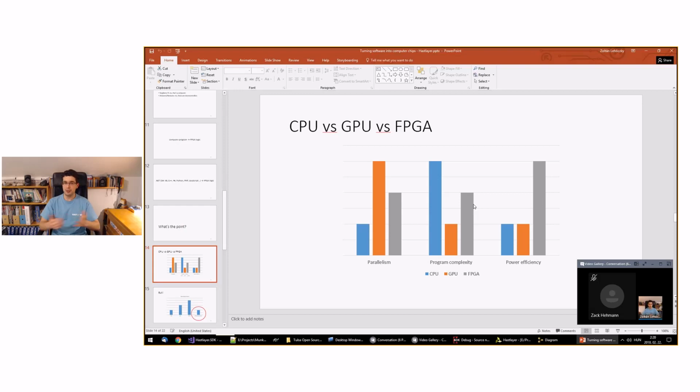As for FPGAs, you can hash out something fairly quickly, although FPGA development itself is 1 or 2 orders of magnitude slower and more expensive than programming. But with FPGAs, you can still roll out something fairly quickly. You can buy an FPGA for maybe a couple thousand dollars, but that's it. With ASICs, the development is much slower and much more expensive. You have to be very careful because you can't change an ASIC. And then finally, when you have the design, you have to manufacture it, which is only feasible if you want to sell tens of thousands of units.